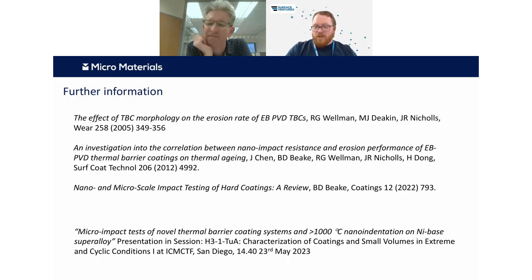So there's a question here from Doris who has asked, do you prefer the rectangular or the Gaussian distribution for impact distribution? Well, we're still learning with this test technique, but I suspect that the Gaussian is effectively quicker. I think you're going to get more damage more quickly with Gaussian. I think in certain erosion situations, these gas gun type erosion tests do produce a sort of natural Gaussian distribution of impacts. So I think you simulate those more accurately by doing that. But in terms of other damage situations, maybe rectangular are better. So I suppose it just depends on exactly what you're trying to simulate. It's not really an answer, but